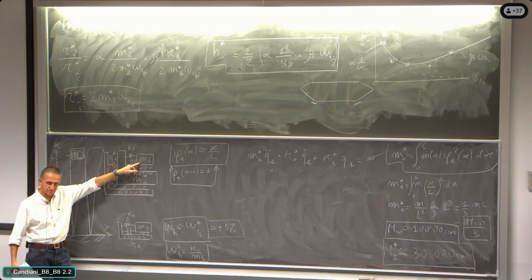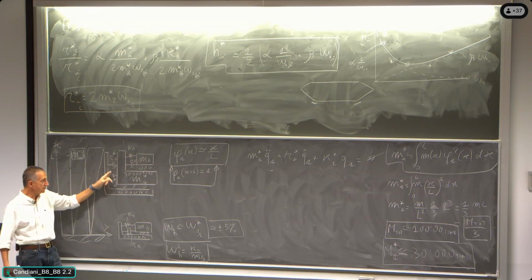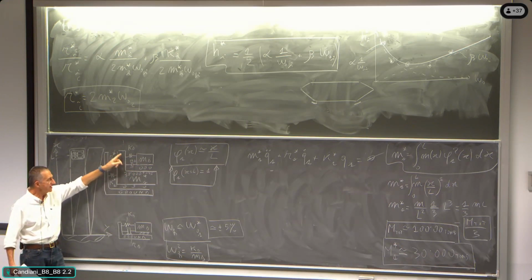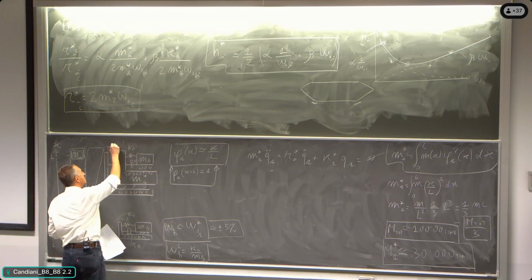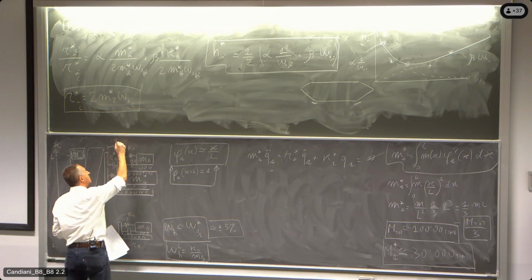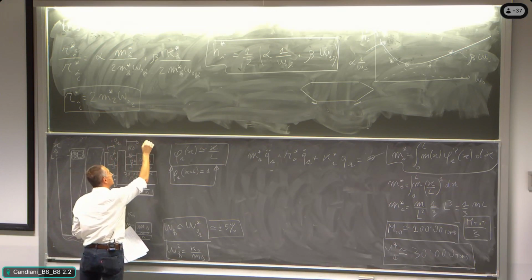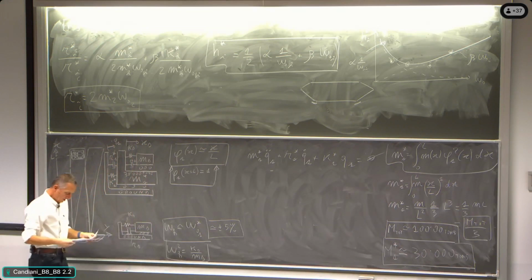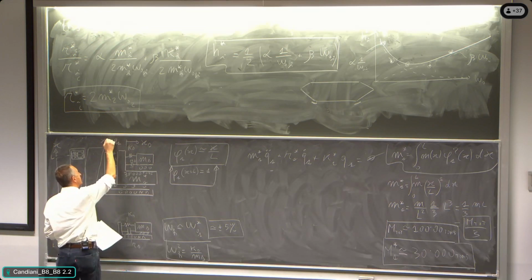And the inertia here is associated to the acceleration of that mass, all right? The acceleration of that mass is the addition of Q1 two dots plus X damper two dots. So this is Q1 and this is X damper. In my opinion, in the drawings here, I wrote this Q1 as X1.